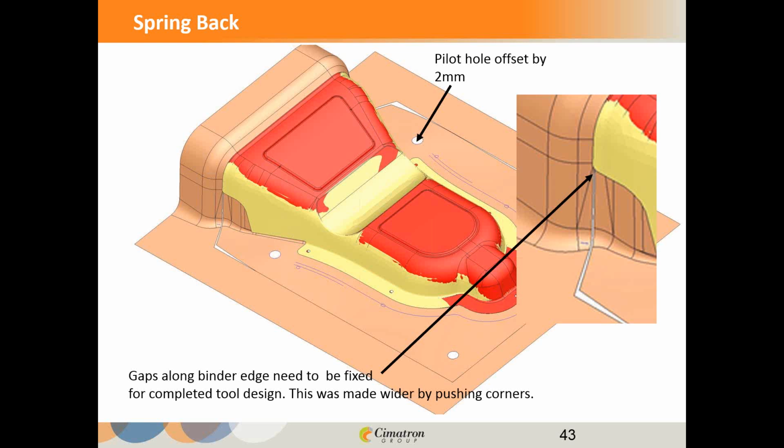You can see that just that slight adjustment in moving the pilot did affect the outcome of the calculation. It affects the total deformation and springback, which tells me that maybe when I do offset a pilot, I'm going to pick one that's further away from the part so it has less of an effect, or put it in an offset location where I know it's not going to cause a problem to the deformation. Something to think about, as we look at the detail level that we're getting into working with this.